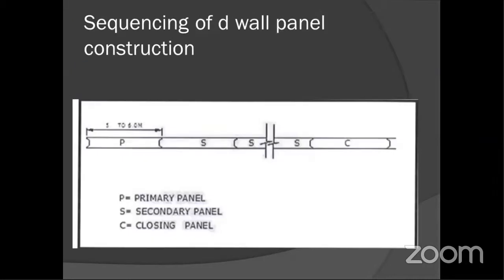See, if you can see my screen, this is the sequence of the dual panel. See, first we are going for the primary panel. So in the primary panels, in dual construction, after putting the cage and all, we have to put the stop ends. That should be waterproofed.